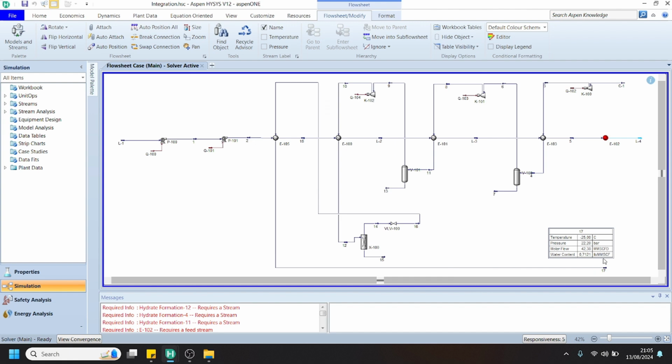So as the HYSYS calculation, we obtain that the water content is approximately 0.7 pound per mmscf or million standard cubic feet. So we obtain that we can multiply this value by 21 and obtain the ppm volume, and we obtain that this specification is already satisfy our specification. It's actually 15 ppm.